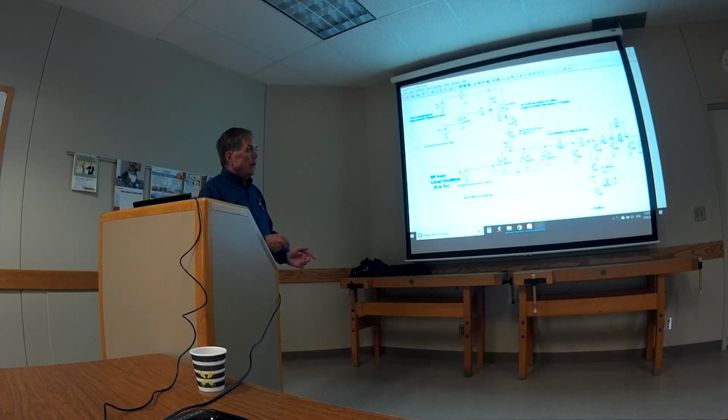And so when it's in transmit mode, I'm just showing you, these are disconnected. It's essentially grounded because you're getting a big signal coming through here. This is only 7/10 of a volt high, so it doesn't hurt anything. It doesn't hurt the receiver. That's your TR mechanism. And then you can see the signal going all the way through.